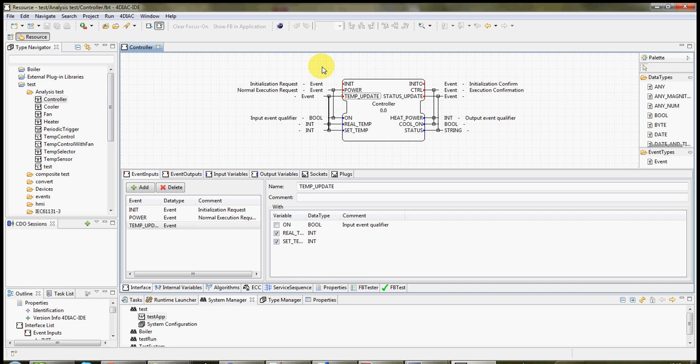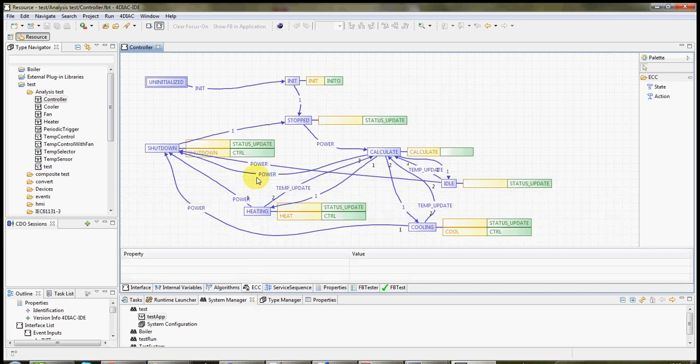In our timing analysis for the IEC 61499, we gather WCET information for all input events of a function block. The WCET of a basic function block is determined by analysis of its ECC. For each input event, we find all possible ECC runs and gather information on WCET values of executed algorithms and produced output events.